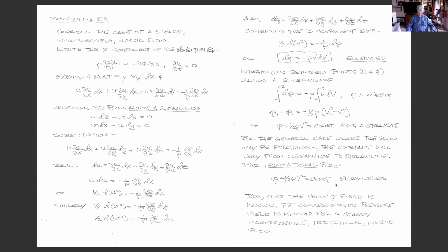It looks like this. Now, to get some insight on that, now you've got a flow field, and we get this boundary layer. But a boundary layer has viscosity, and the flow is zero at the wall, and a short distance out from the wall, you've got the potential flow velocity. Within the boundary layer, you have viscosity effect.